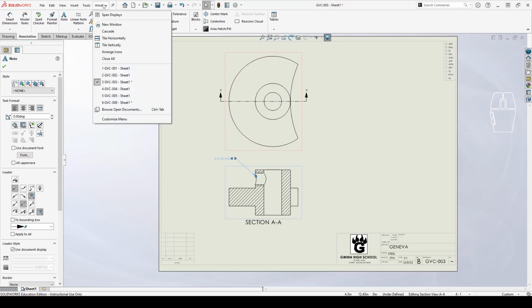Okay, let's jump through the rest of the drawings. You guys have to add the dimensions, so make sure you add the remaining dimensions and center lines. Remember, there are no hidden lines on the section view. You won't see a hidden line in this top view. Yeah, you will. You'll see the hidden hole.